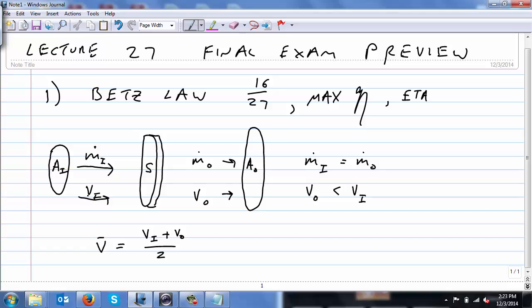What else am I kind of missing from this thing? What might be important that you might want to know to calculate the power or the energy in the air? The density. Yeah, you'd want to know the density. And so upstream here, you've got density in. Anybody remember what that funny looking P is? Rho. Okay, cool. And then here's rho out. The other thing to consider is that rho in is going to equal rho out.